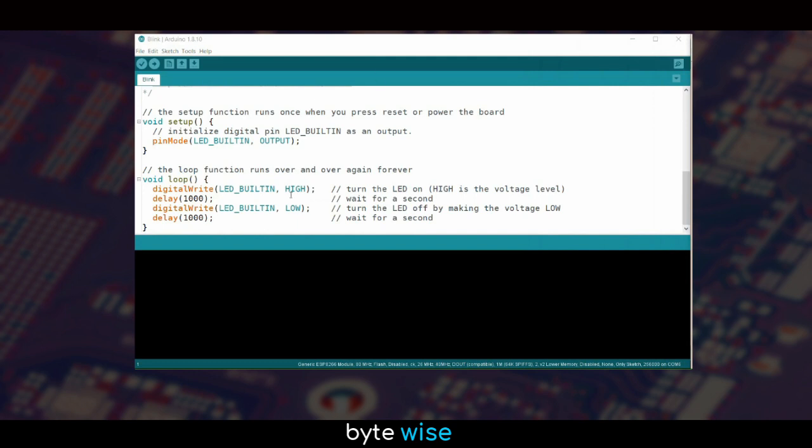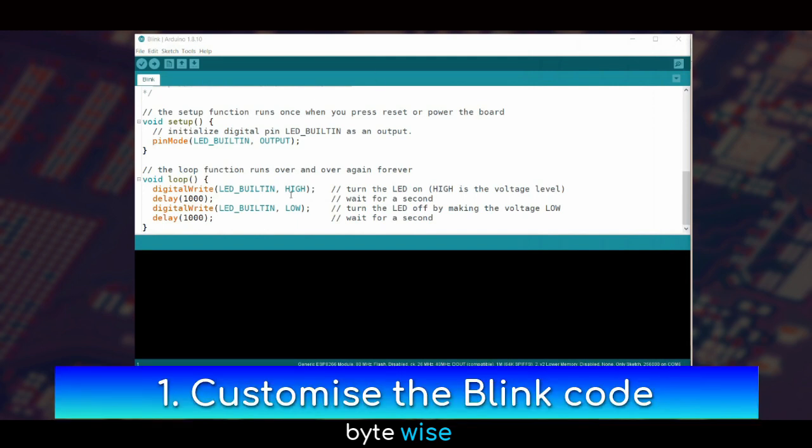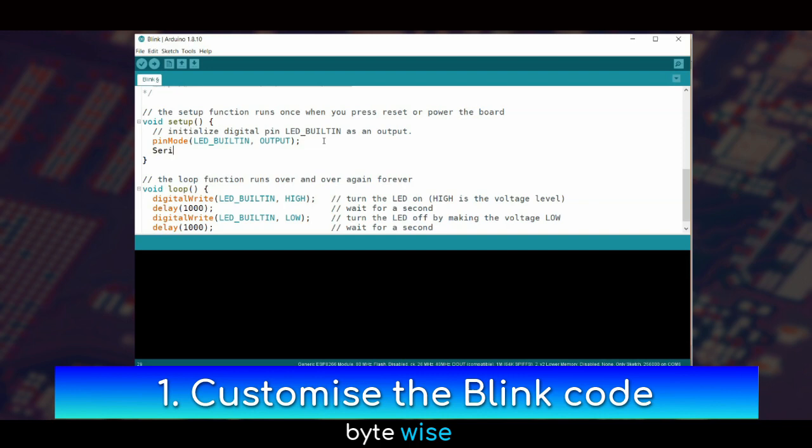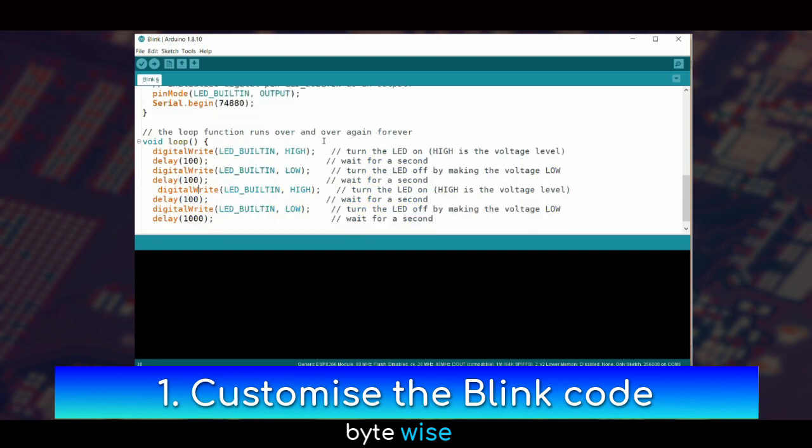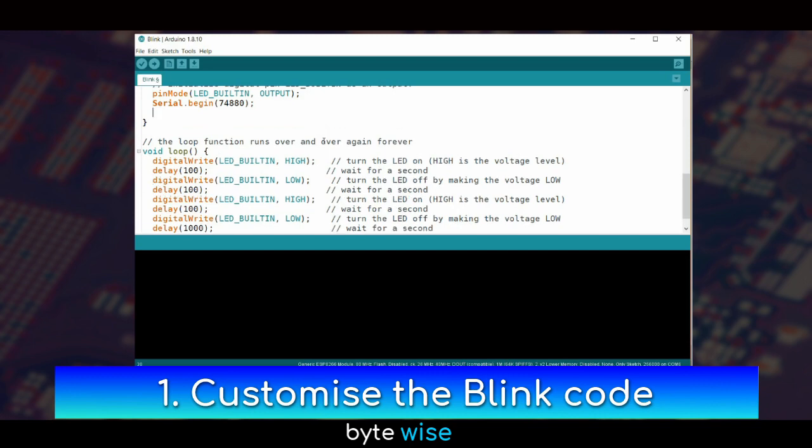To test the construction of a newly built project, it's a good idea to run a simple program that's known to work. We're using the standard Arduino blink program, adding in output to the serial port. I've altered the blink pattern into 2 short flashes to make something more distinctive. You can find the blink program under File, Examples, 01 Basics, Blink.